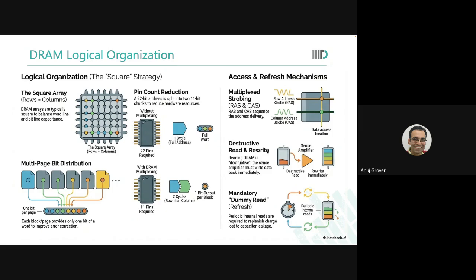Are you with me? This was where we left. We had started with the fact that because we have this configuration, we would need to have 2 additional signals, RAS and CAS, which would tell which address is being sent on the address bus.